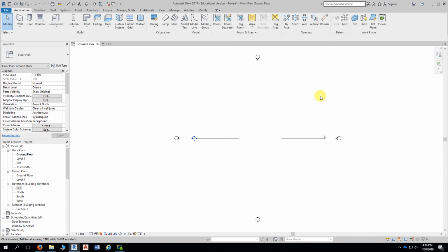Now, in this view, you've got these markers here. See this, the one at the top, one at the bottom, here left and right. So what are they? Directional markers. Yeah, they're your elevation markers. So top is north, bottom south, left is west, right is east. Okay. So when we are drawing up our building, we make sure that we actually are well within the elevation markers in the view.